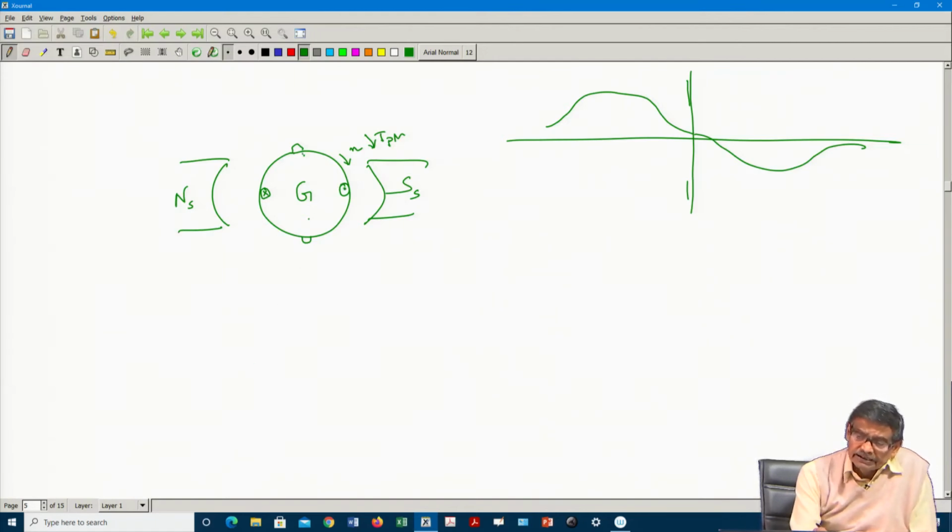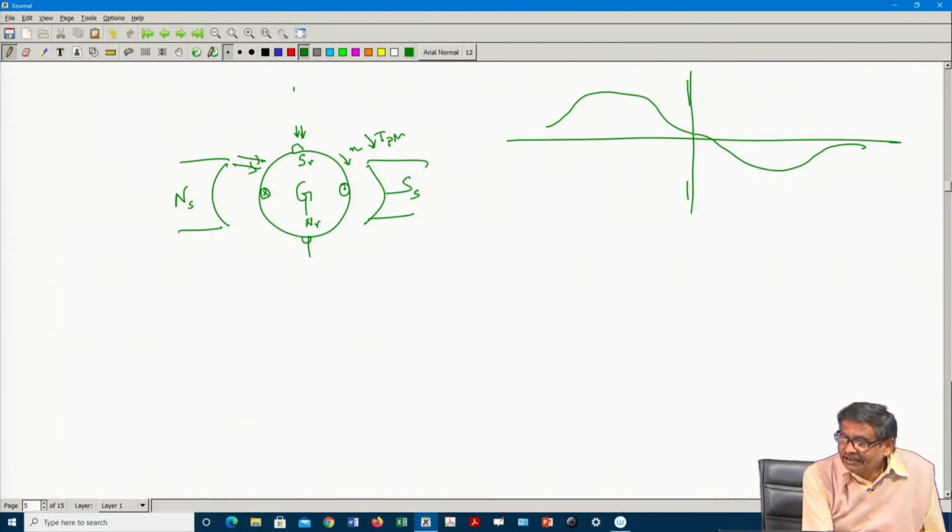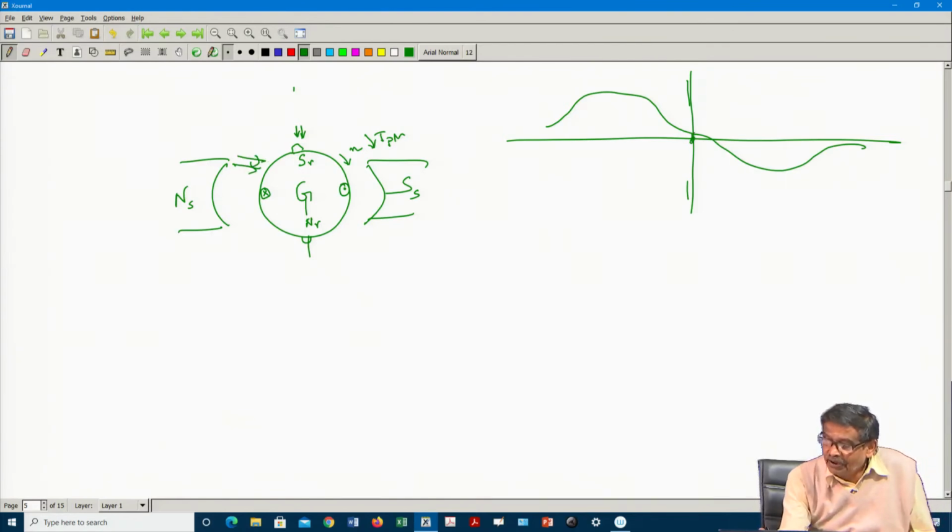So, in the armature this will become SR and this will become NR, lines of force will come out. Therefore, you see now in the quadrature axis, some lines of force in this direction have been created, and the north pole also creates like this. Therefore, in this position now it is not 0, it gets distorted, there is some flux here.